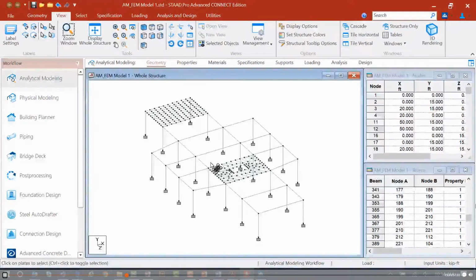And so for both of the methods that I've shown you so far, the super element method using the add plate tool or the generate mesh tool, you would have to focus on one area at a time. The reason for that is because I want it to connect to these interior members and to the tops of these interior columns. And using these two tools, the only way to do that is to focus on one bay at a time.